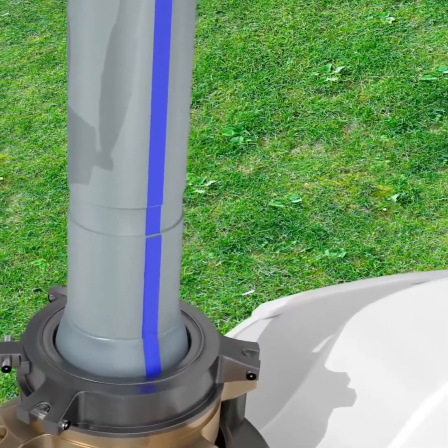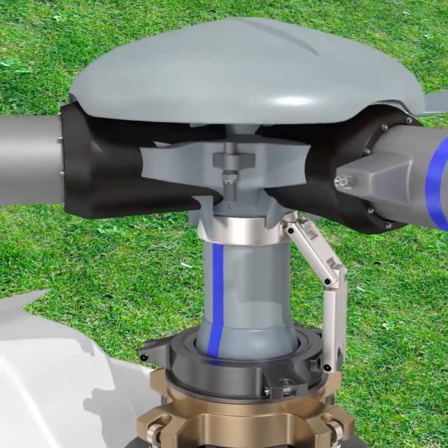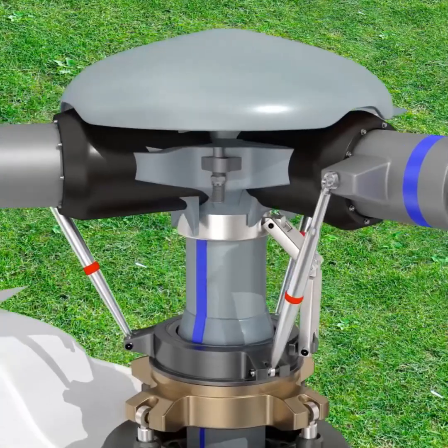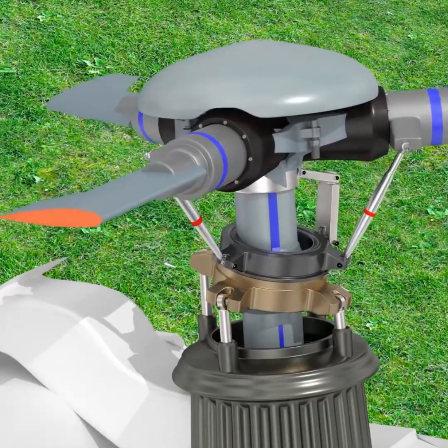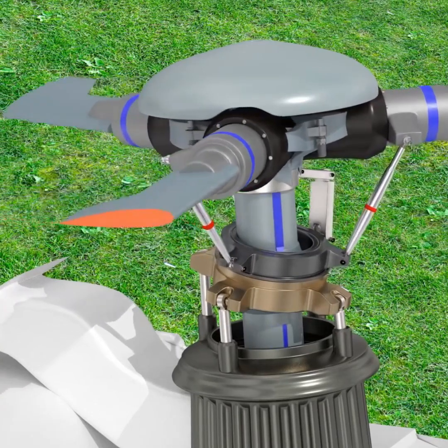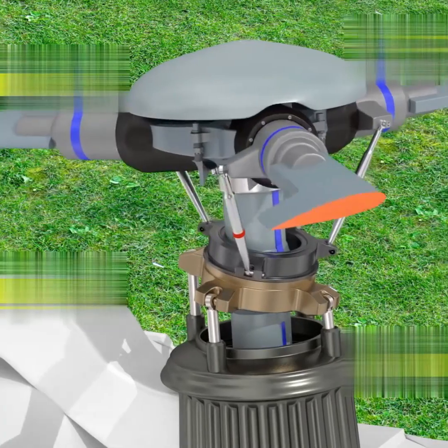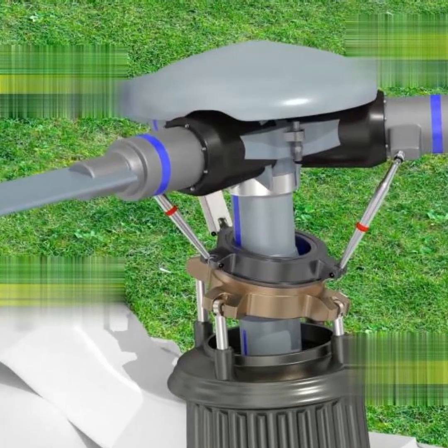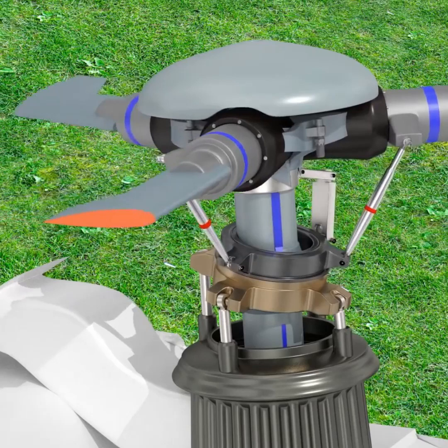The upper swash plate is connected to the rotor shaft by a drive, causing it to rotate with the blades. The blades are attached to the upper swash plate by control rods. Interestingly, by simply tilting the lower swash plate, we can change the angle of attack of the blades. This means that if the swash plate is tilted, we can maintain a positive angle of attack on the front side and a negative angle of attack towards the rear of the rotor disc. In short, the tilted swash plate generates torque. This type of control is called cyclic pitch.